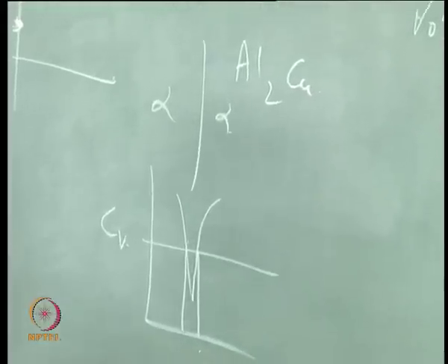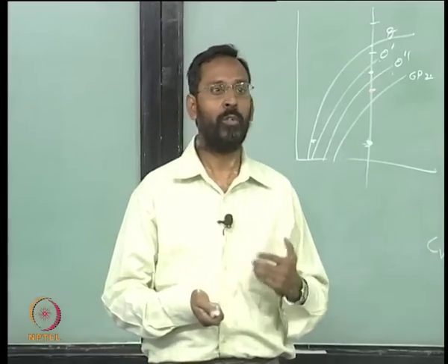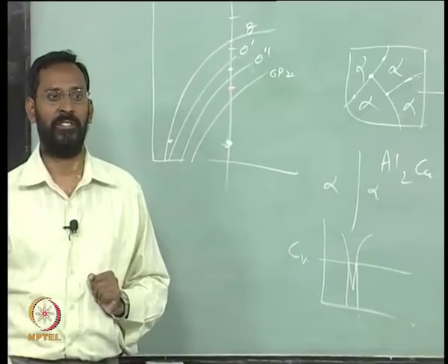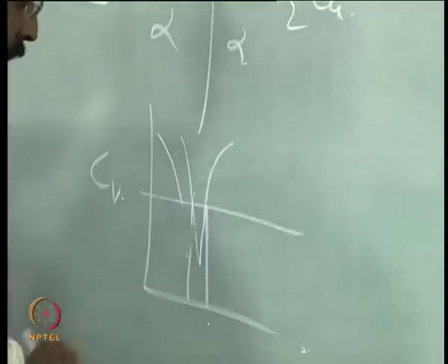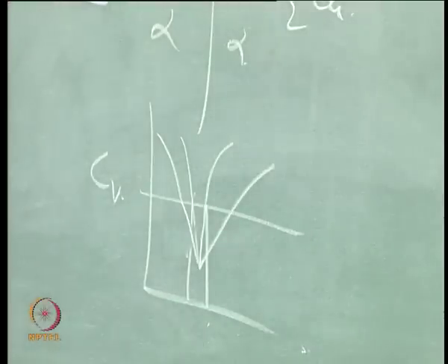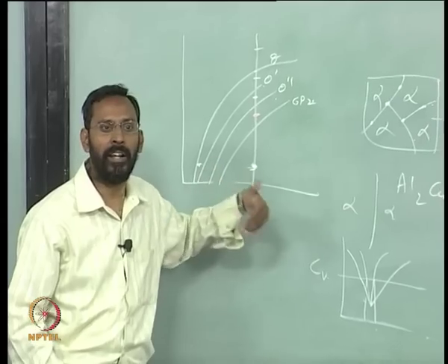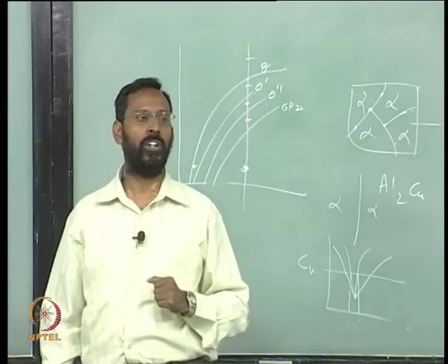And in fact, it depends on whether you are quenching very fast or quenching slowly. Sometimes if you are quenching slowly, then this region is going to be larger. You may see something like this. That means there is enough time for the vacancies which are farther from the grain boundary also to migrate towards the grain boundary and then get merged or annihilated into the grain boundary, and if that is the case, then you would see the PFZ will be larger.